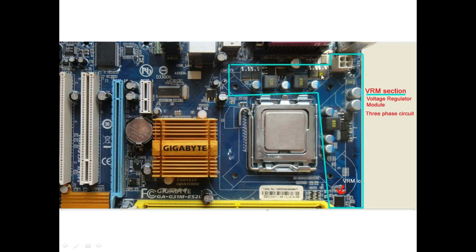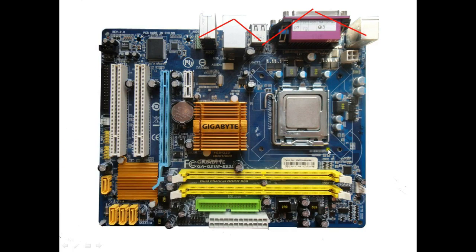And there are several components present in the VRM section, like transistors, the coils, the capacitors, and more IC, which we call as a VRM IC. This VRM IC is sometimes referred to as PWM IC or oscillator IC or regulator IC. So here 1, 2, 3 coils are present, which indicates that it is a 3-phase circuit.